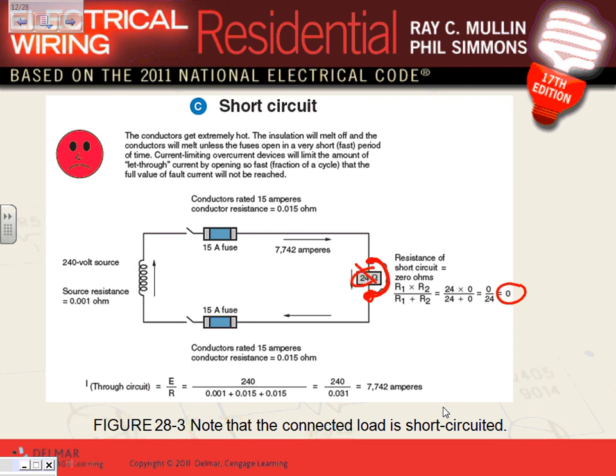So what happened is, you guys remember the 24 that used to be here? That's gone. So now, the only impedance is the impedance of the two conductors and the source. Thank God there is some impedance. Otherwise, you would burn the equipment completely. You have to have some impedance. So look what happened here. This becomes very interesting. We take the 24. The only impedance is the impedance of the cables and the source, mostly the cables. So it's divided by a tiny little number. So look at that current that's going to grow. Math, just divided by a very small impedance.